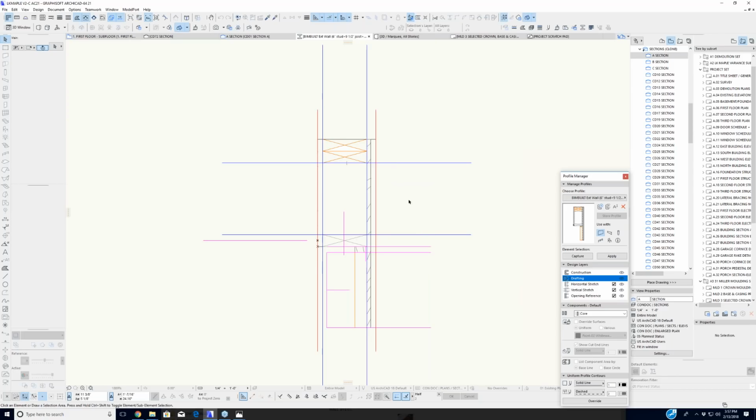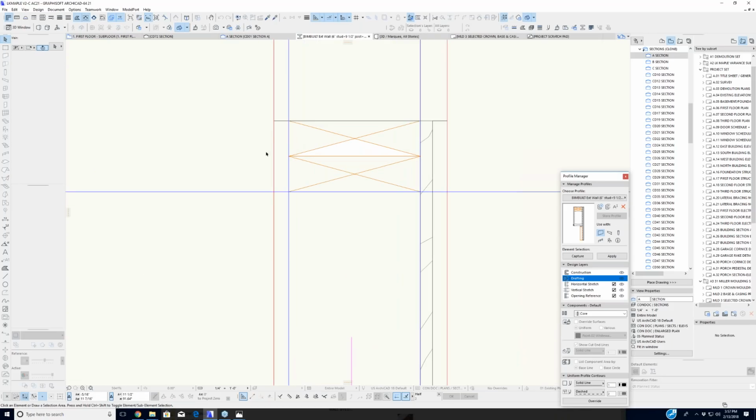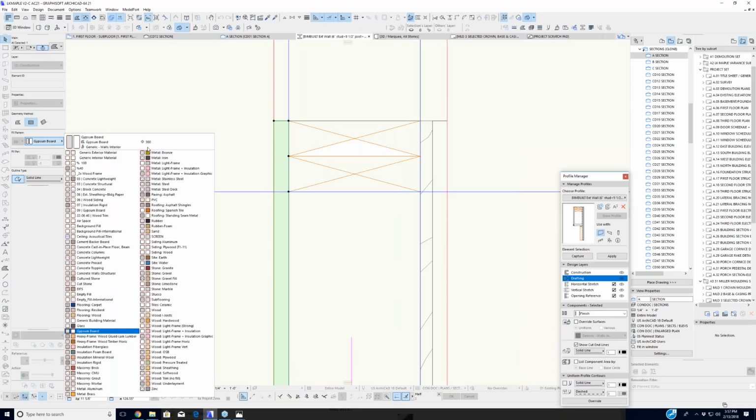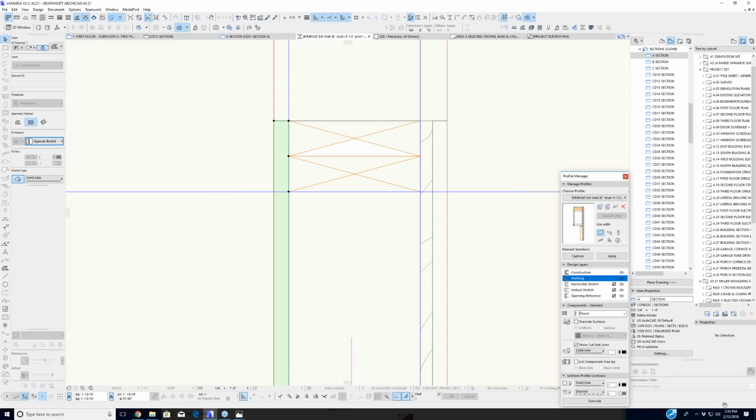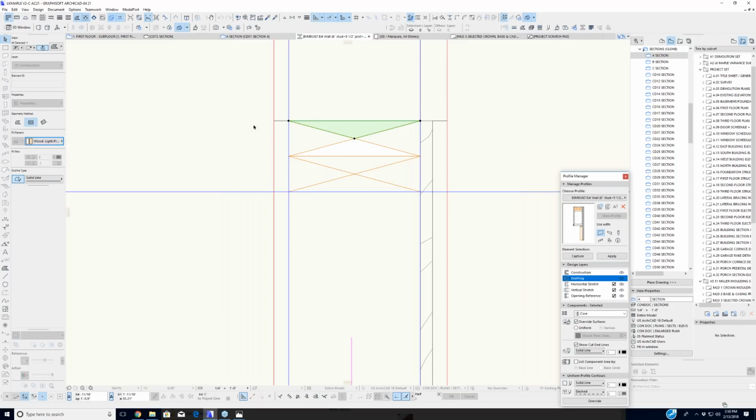The other thing is just, can you select the individual triangles, at least 2 or 3 of them, one at a time, and say what they are? Yeah, so this right here will be, if you look on the far left, is gypsum board. If I click on gypsum board, it's only a building priority of 300. Now in that cross section, you could see that ceiling came marching across, it kept going, and it disappeared when it sat on top of this stud. This top plate is a fill called wood light frame strong, and you can see the 300 is going to be smaller than the 647. So immediately, without getting into solid element operators and all that stuff, it's automatically deleted.